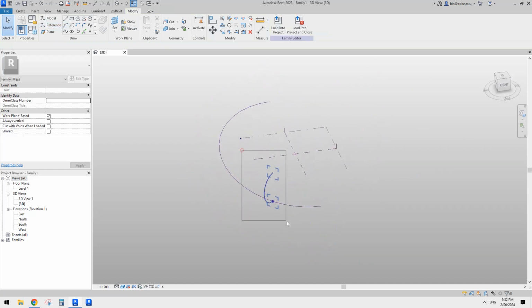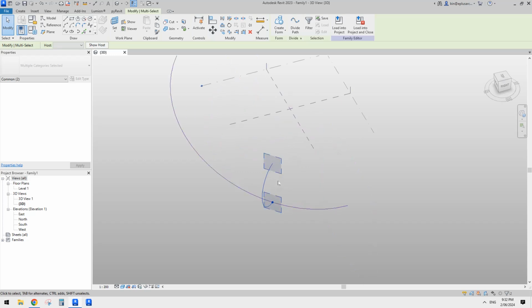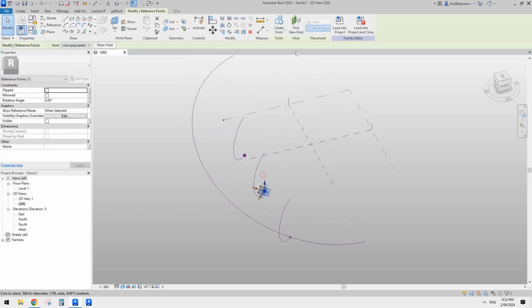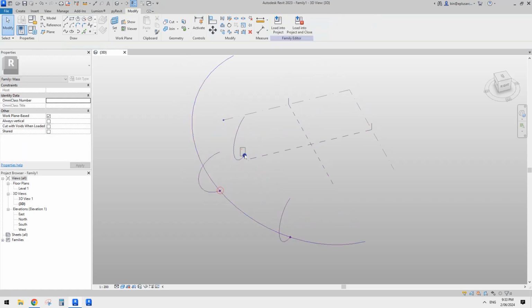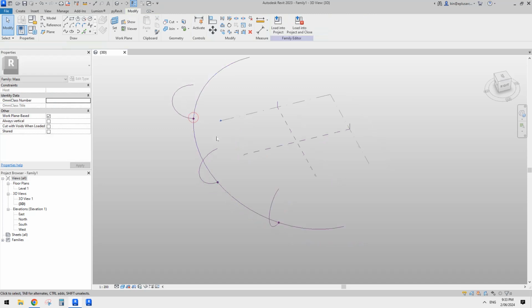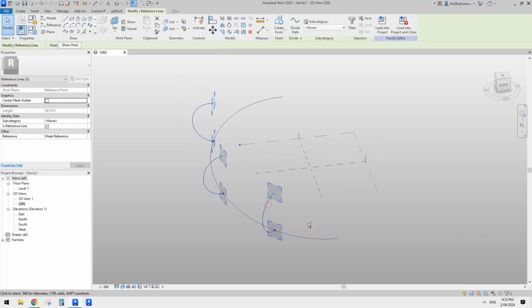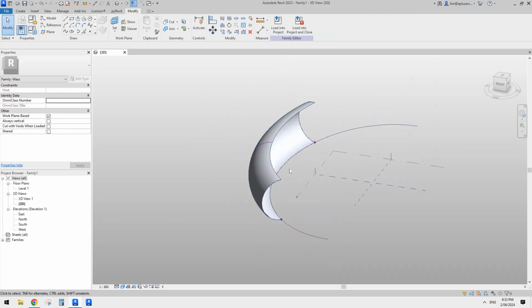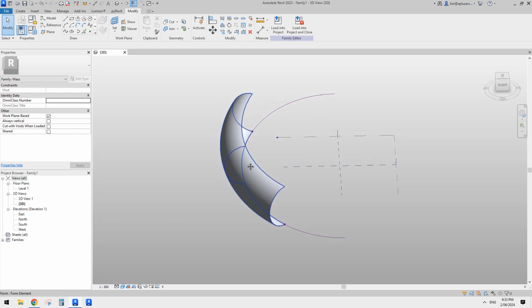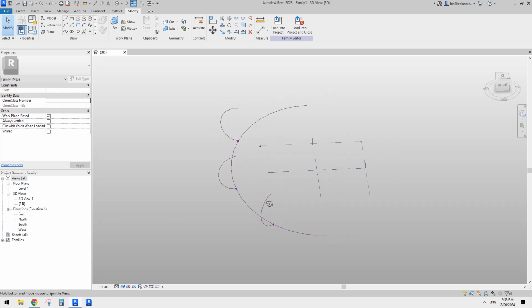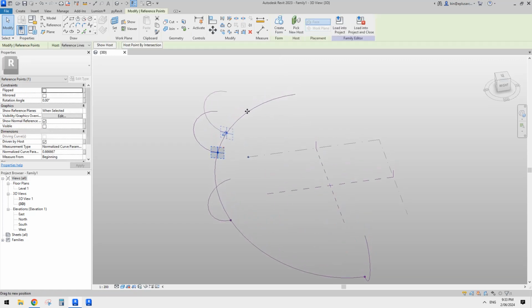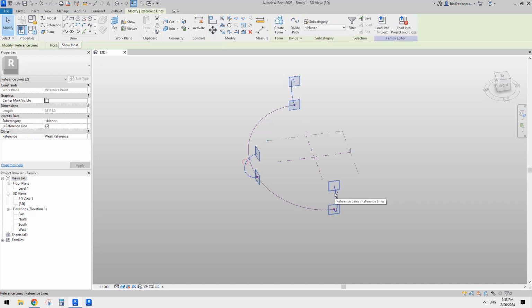Then we're going to select the point and the half circle, CC. I'll copy 2 times, and then select the point, pick new host, select the point, pick new host. So now we can select these 1, 2, 3 together with this path to create a shape. Sometimes we need to do it when they are close to each other, so I'll show you why. If I Control Z, drag this to this end, and then drag this to this end, and then try to create a shape using the same path and profile.